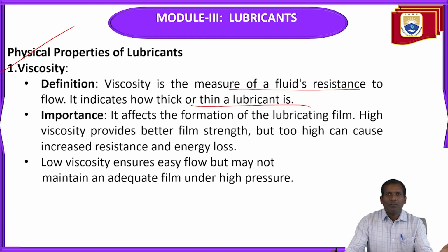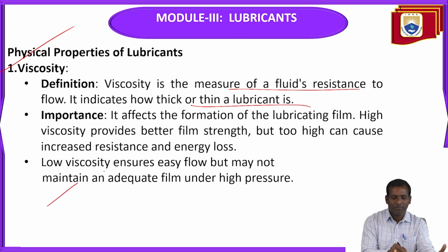The importance of viscosity is that it affects the formation of the lubricant film. High viscosity provides better film strength, but too high can cause increased resistance and energy loss. Low viscosity ensures easy flow, but may not maintain an adequate film under high pressure.